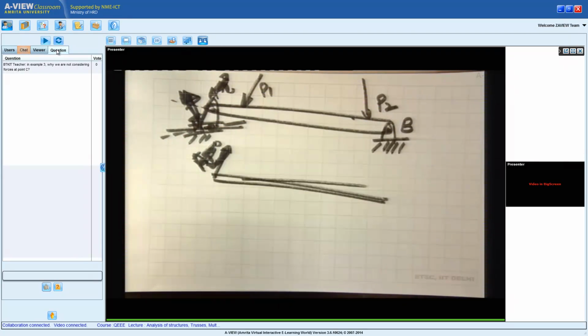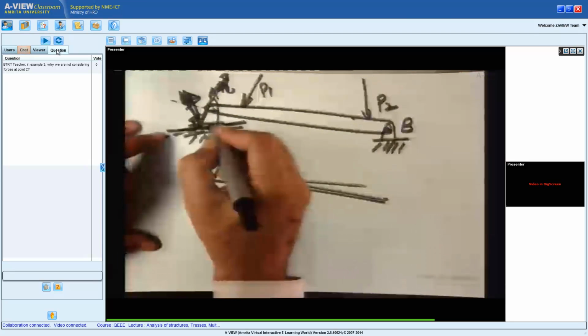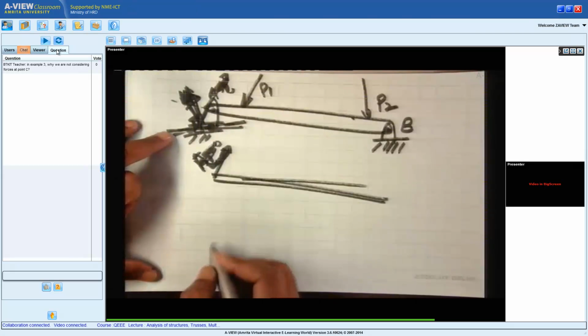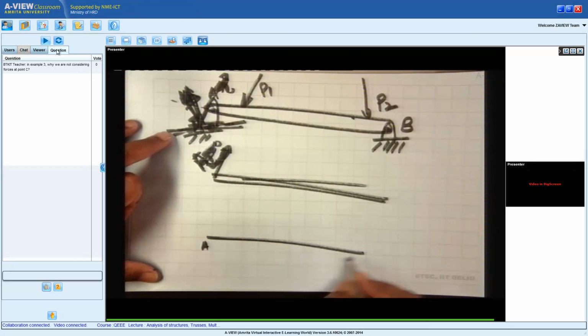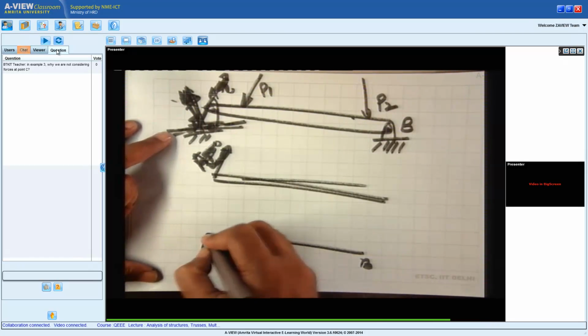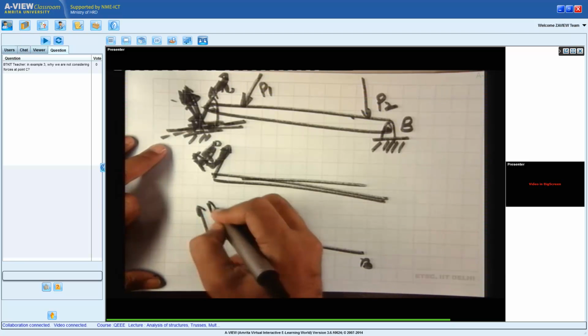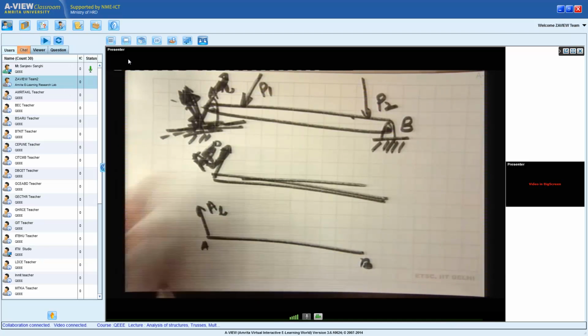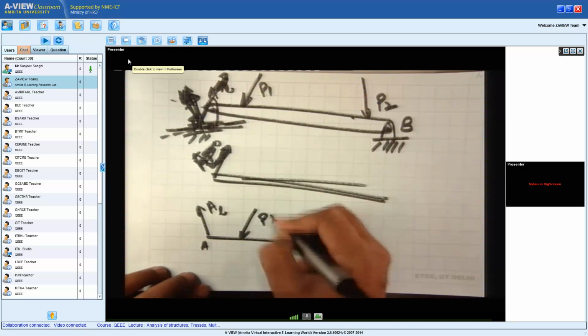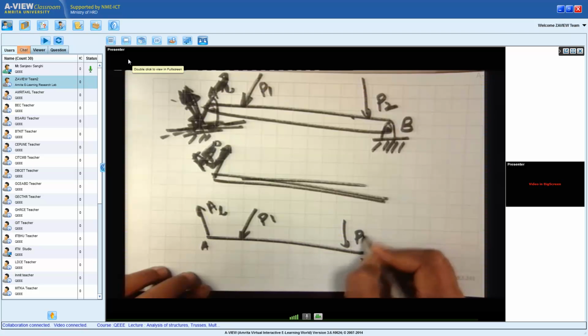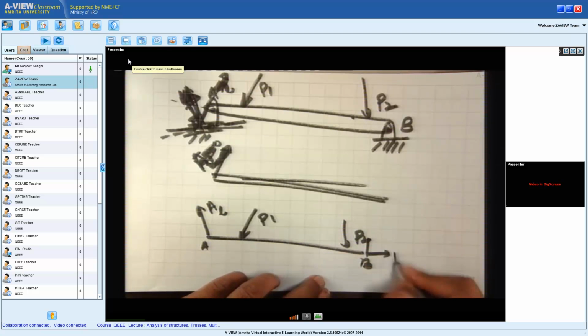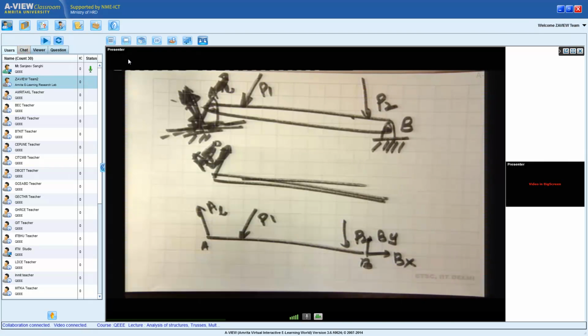And I think I may have made an error in the last class. So perpendicular to this is this direction. When I draw the free body diagram of AB, I have to show the force at A only in the direction perpendicular to the roller motion. Okay, I'll just call them P1, P2. Now AB, I'll just mention, is not a two-force member.